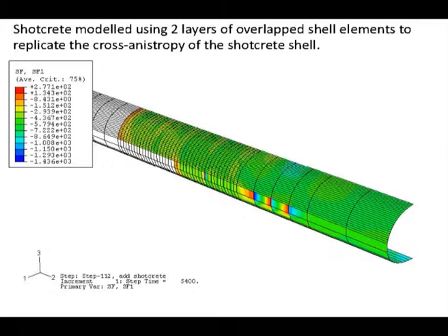When we ask them, what stiffness? The guy said, I don't know, because most tunnels are designed to be stable in the circumferential direction. So all I did was put a few starter bars there. Okay, so what is the stiffness of the starter bars? Obviously, it's going to be much lower. So you have a plate element that is, in fact, cross-anisotropic. As a result, we have to model that cross-anisotropy. So this is one of the things we actually model.